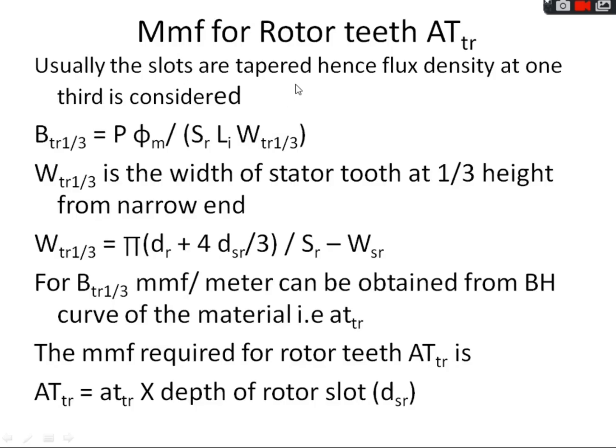Magnetomotive force required for the rotor teeth is calculated in the same way as we have calculated it for the stator teeth. For the rotor teeth, we are again assuming that the rotor slots are also tapered, and we are considering the width of the rotor slot at 1/3 height from the narrow end, as we considered for the stator.